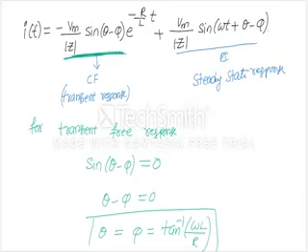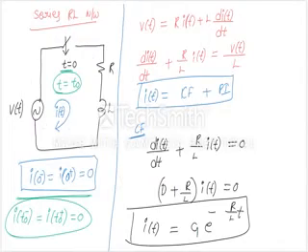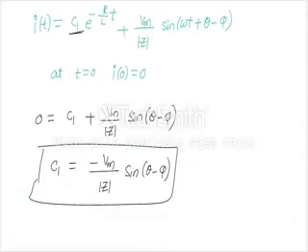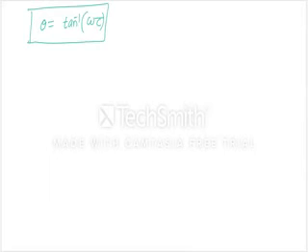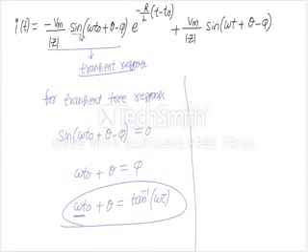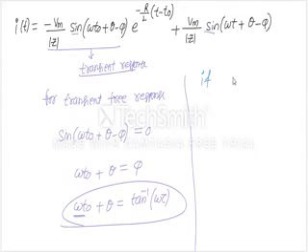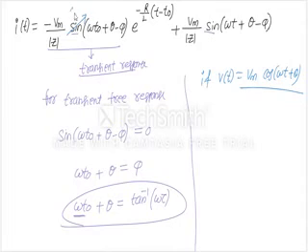Now one more thing here. The supply we have taken is Vm sin omega t. That's why the expressions we got have a sine. If I have taken the supply V of t equal to Vm cos of omega t plus theta, then in place of sine we'll get a cos, except that no change.